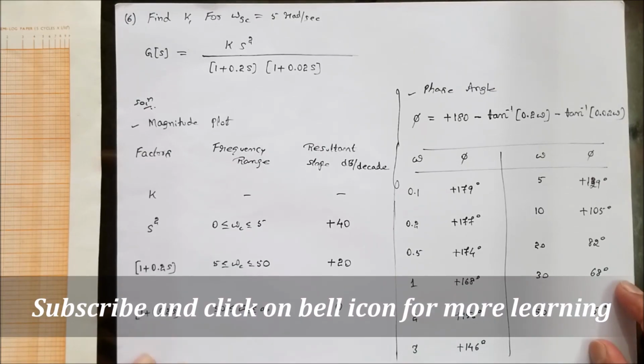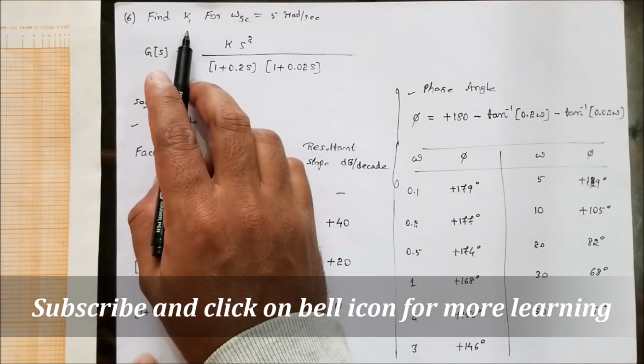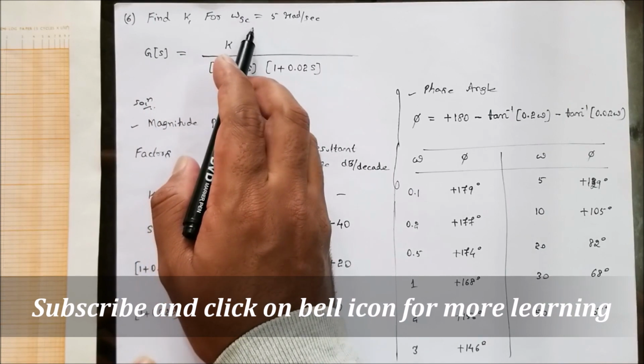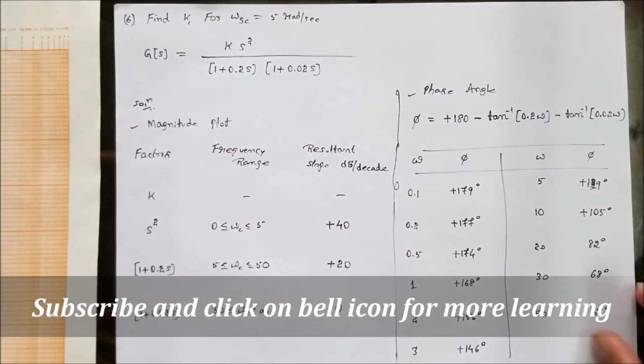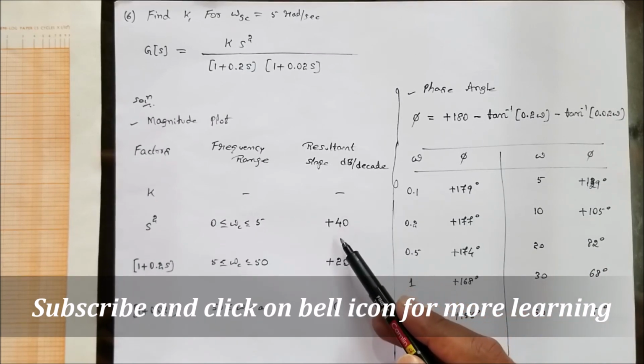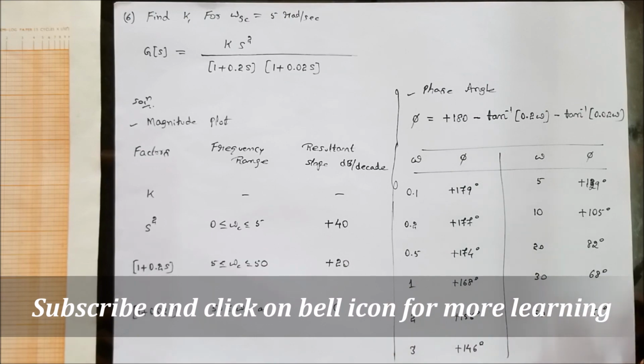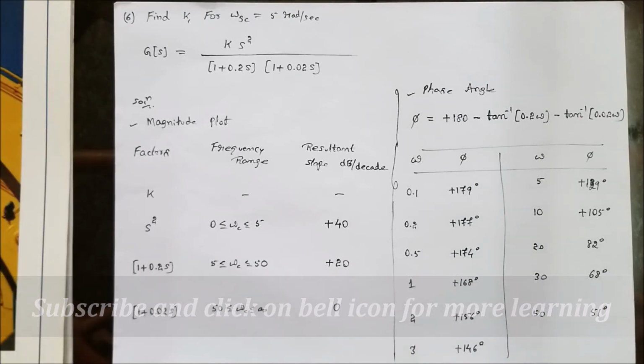Moving ahead for step number 4, I want to draw the Bode plot for our problem number 6, wherein I want to find the value of K for the gain crossover frequency to be 5 radians per second. Correct? So now if you observe, the maximum slope I require is plus 40. Very, very important. It is positive 40.